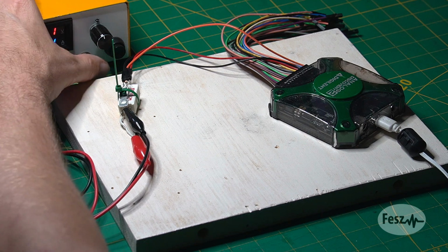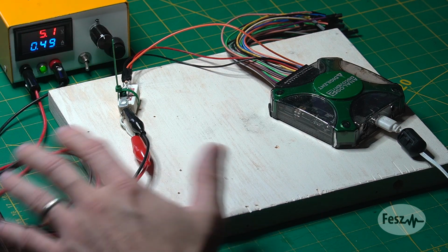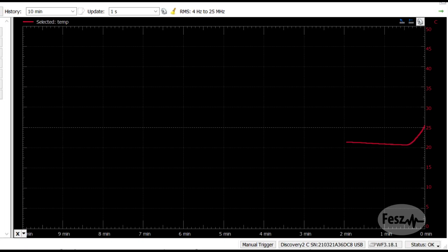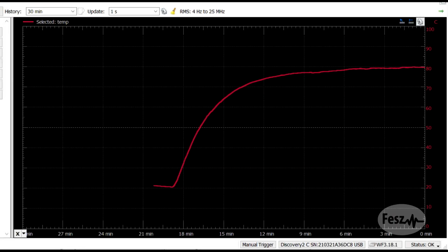Now, if you've ever performed a thermal measurement, you will know that temperature does not change instantly. Once you start up a circuit, here I'm measuring a power resistor using an NTC, you need to wait a certain amount of time for the steady state to actually be reached. This could be minutes or hours. So the temperature predictions that we get from the basic resistor models are only achieved at steady state. So the instantaneous temperature transfers that we have seen until now are not really the way in which a real-life circuit behaves.